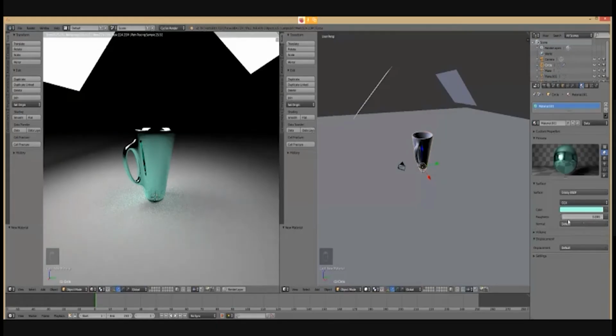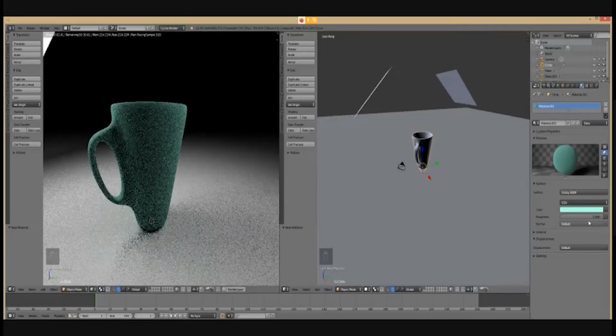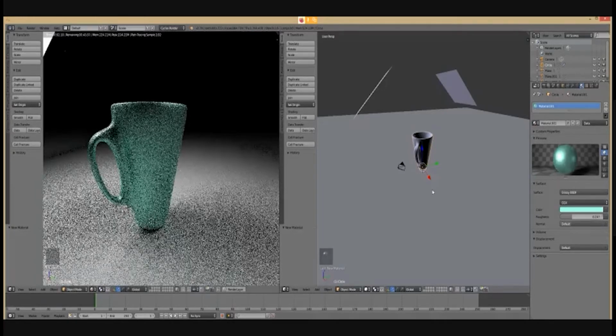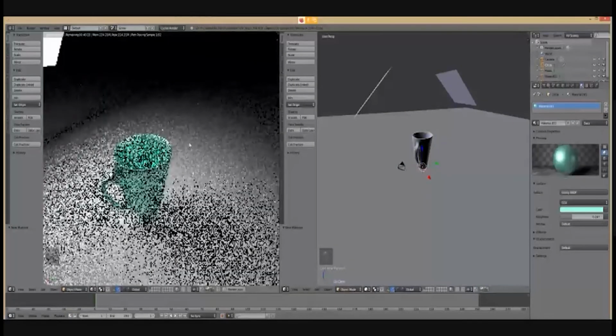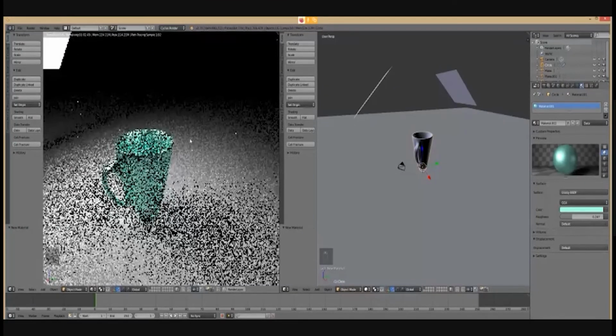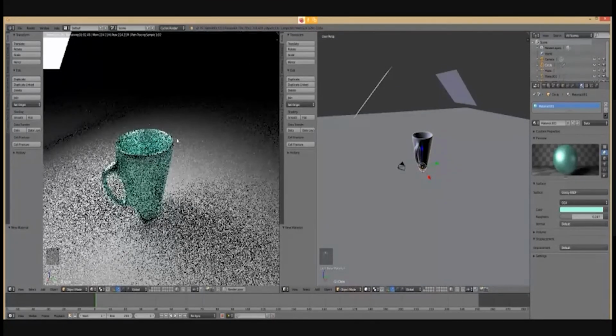If I go all the way to 1, you can only change it between 0 and 1, so 0 and 1 are the extremes. At 1, you will notice the look changes. If I keep it back at 0, it's got this very, very shiny metallic look. However, let's say I don't want a very shiny look, I want a matte finish. So I can slowly change it to whatever value. At 0.247, it's not exactly very shiny, but at the same time, it's not very rubbery. It's got this premium matte finish look.